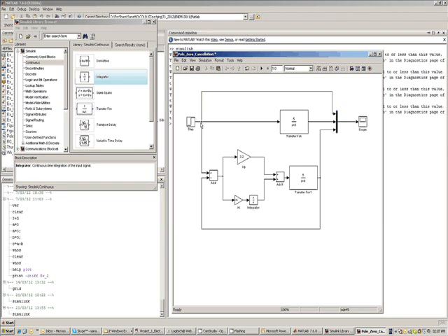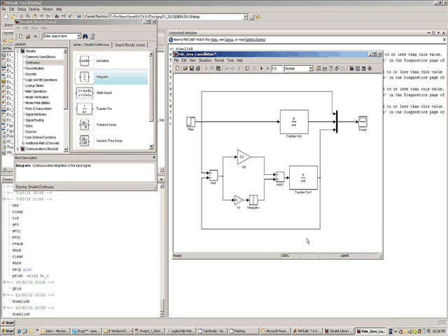So now what? Now if you look carefully, we apply the same step input to the open loop system, take the output, plot it. We directly plot the step input, and we also feed the same input to this closed loop system where I've got the comparison between the reference and the measured output, take the error, feed it to the proportional controller, take the output, feed it to the integral controller, take the output, add the two together, feed it into the input of the system.